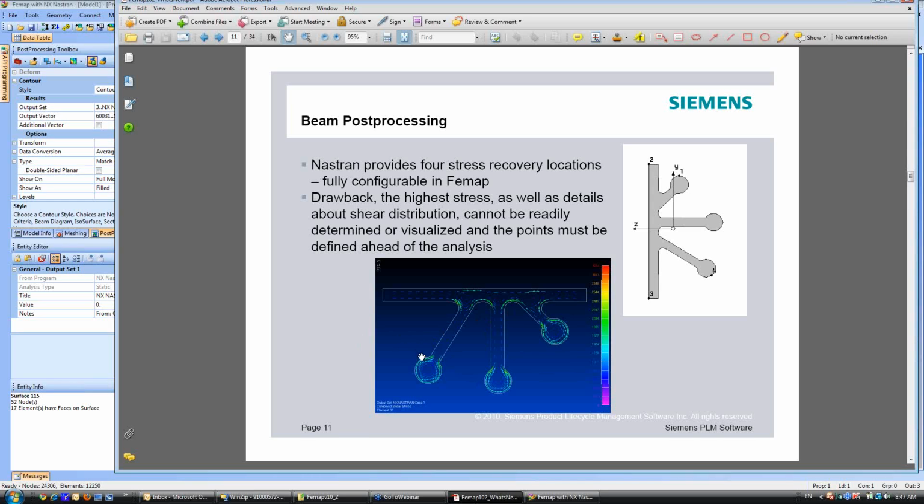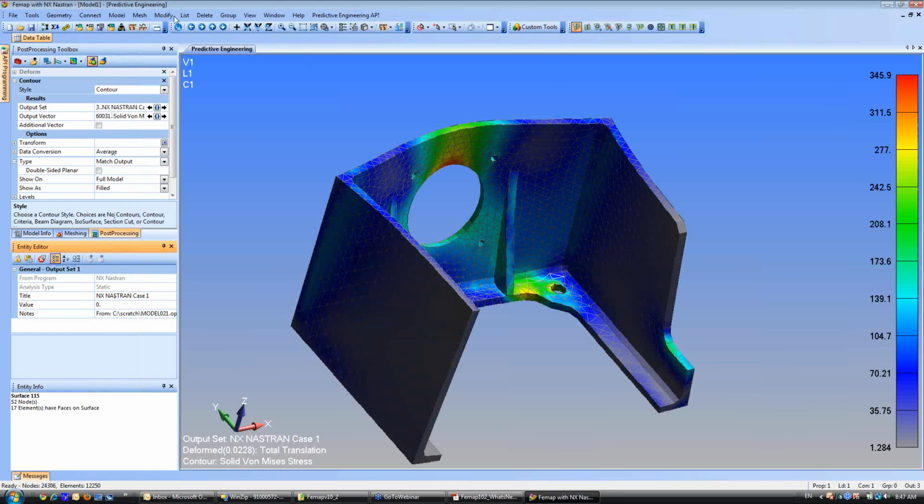For you guys that have been using beams, you probably understand they're the most powerful element in the Nastran library. They're absolutely fabulous for doing optimization studies, quick, down and dirty, but they have limitations. You really can't get detailed stresses on the cross sections of any complicated shape. It doesn't take into account torsion. It'll give you a torsion force, then you have to take the maximum calcs and go through a hand calc to get the derived stress correctly. It's a little bit scary at times. Well, that's no longer. Watch this.